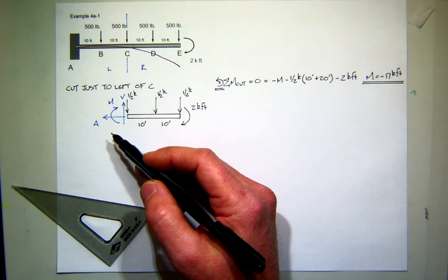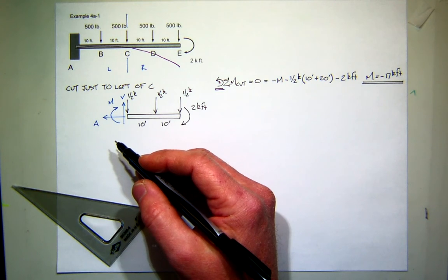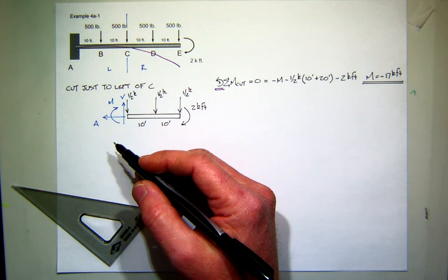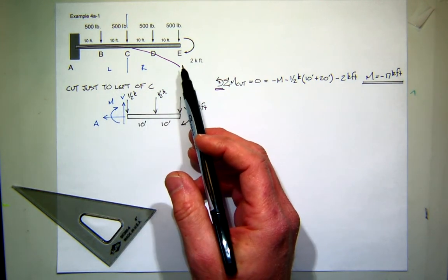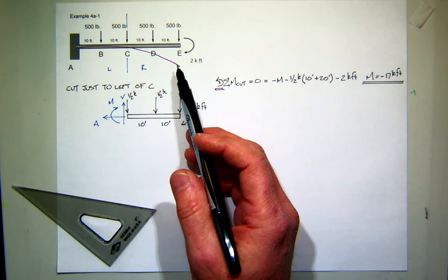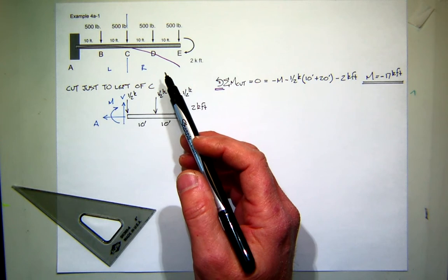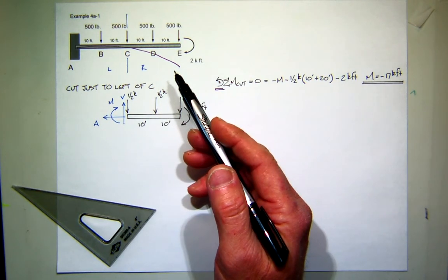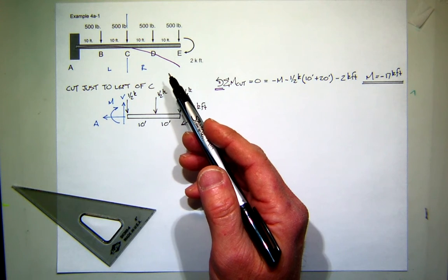If you're designing reinforced concrete, you want to know where that is, right? Because reinforced concrete behaves differently than steel. What if you had a negative bending moment in reinforced concrete like this? Where would you put the steel? Top, because that's where the tension is. So if you just tell some guy, I got a reinforced beam, it's got, I don't know, a moment in it, well, you've got to know if it's positive or negative. That's a big difference. Steel, not so much.